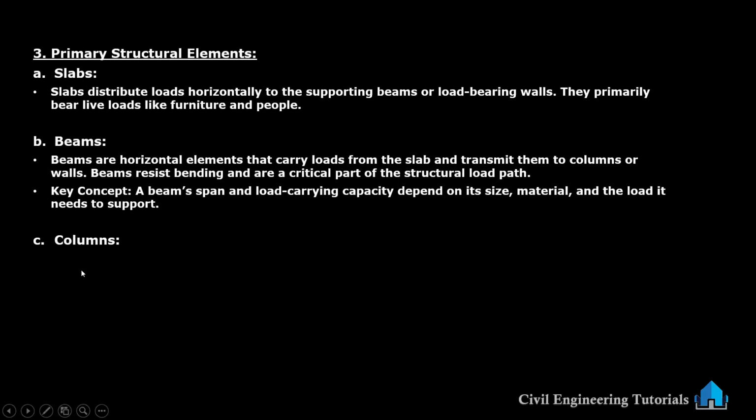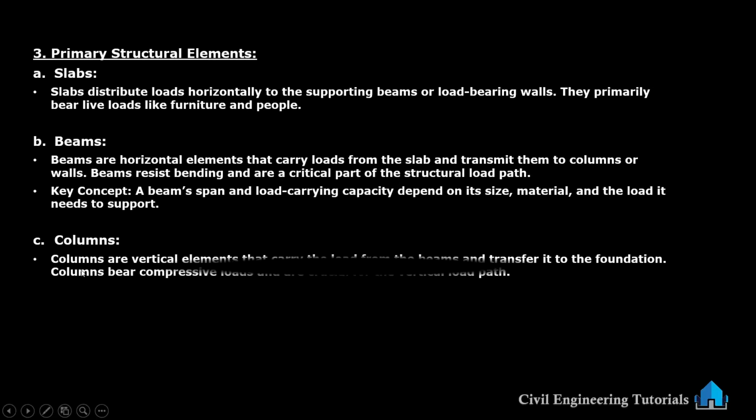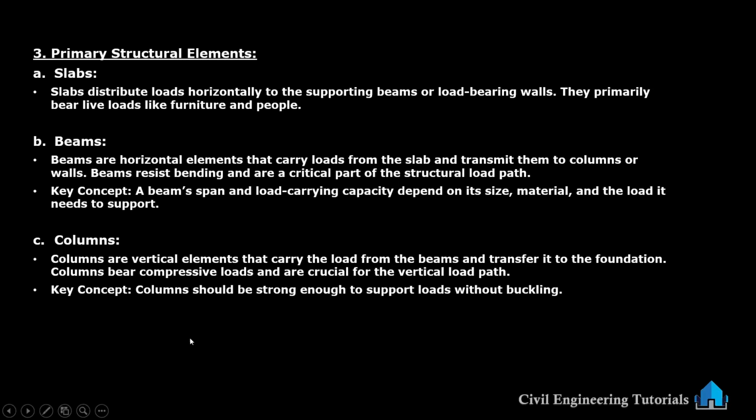Next, columns. Columns are vertical elements that carry the load from the beams and transfer it to the foundation. Columns bear compressive loads and are crucial for the vertical load path. Key concept: columns should be strong enough to support loads without buckling.